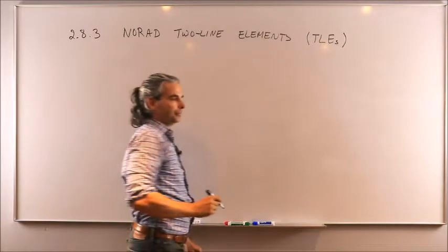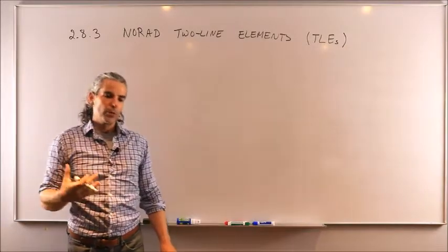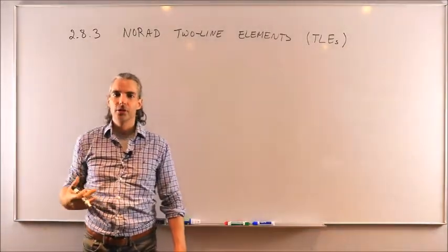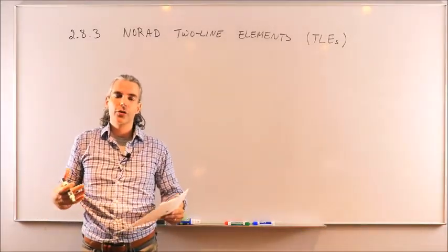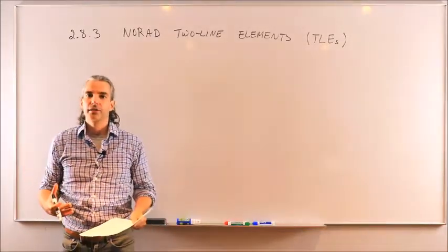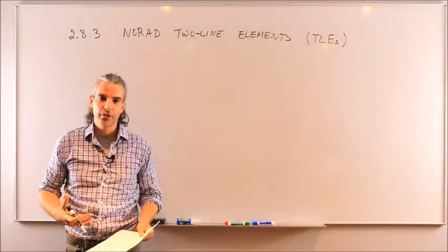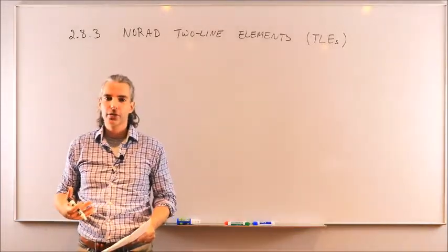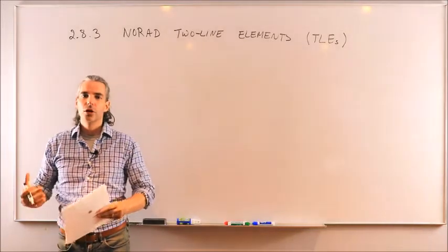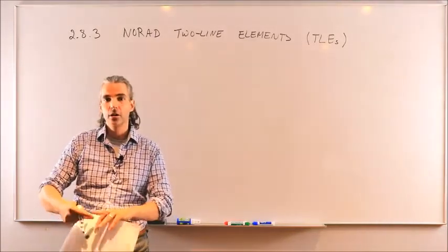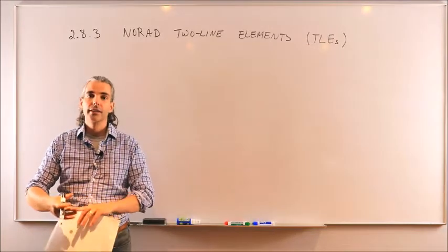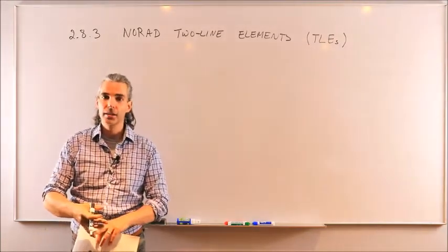So if you remember what we did last time in terms of orbit determination, we derived mathematical methods to convert ground-based measurements, position velocity vectors, or two position vectors, and turn them into orbital elements: semi-major axis, eccentricity, inclination, radian, argument of perigee, and time of perigee passage, TP.